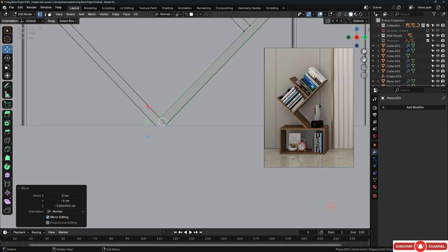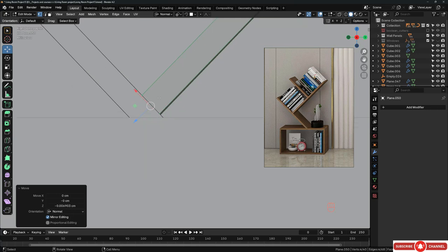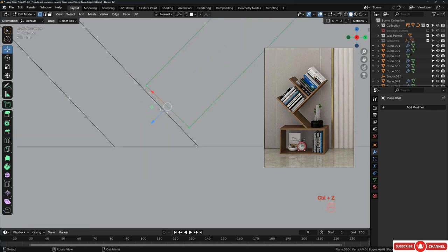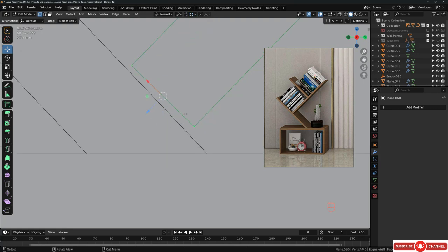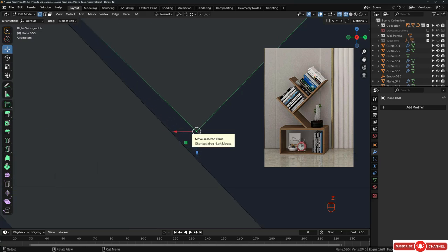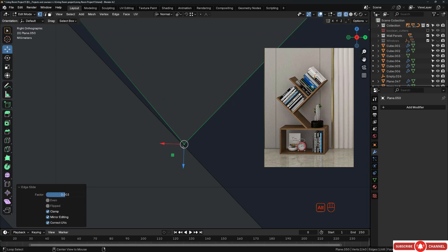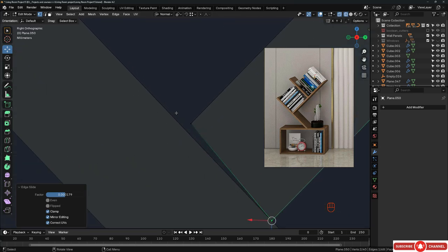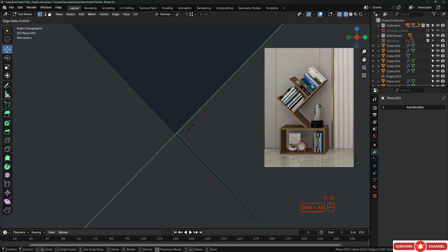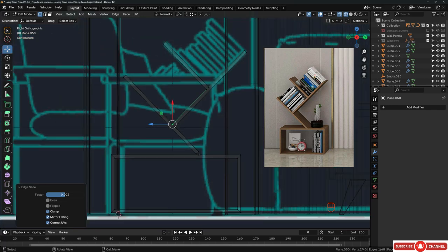But all right, I think here we got another problem. We got a very small amount of twisting happen right here. So actually, it's not quite necessary to do that. So in this case, you can grab this manual like that and hit G twice and hold Alt and push this and align it with this surface like that. And you can do the same for this one, G twice and hold Alt and move it like this. That will be enough.